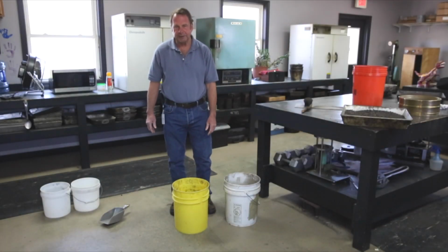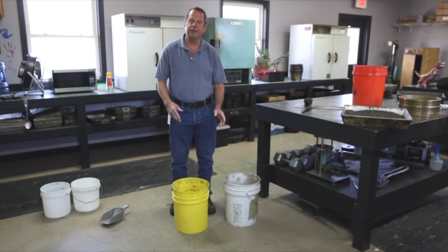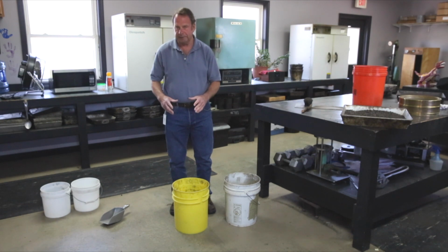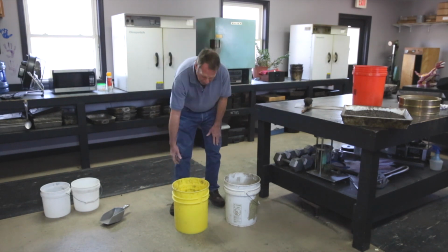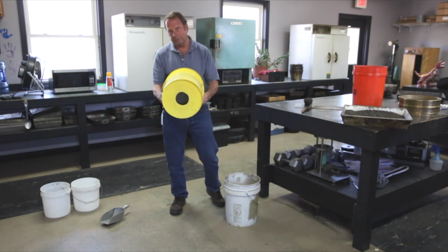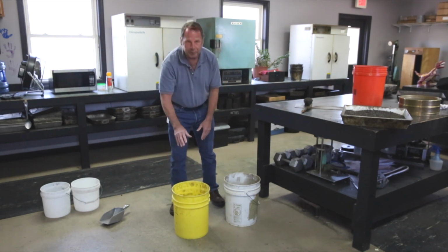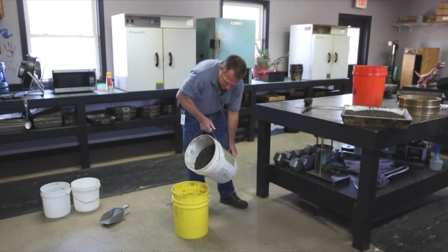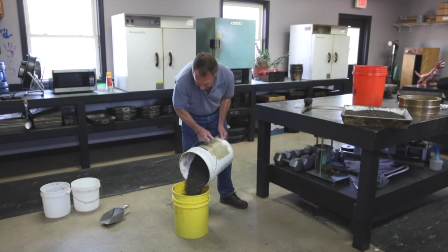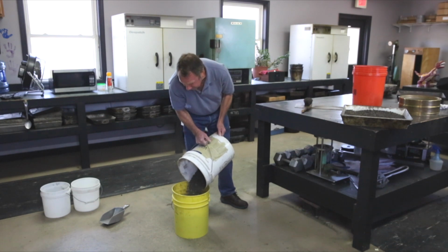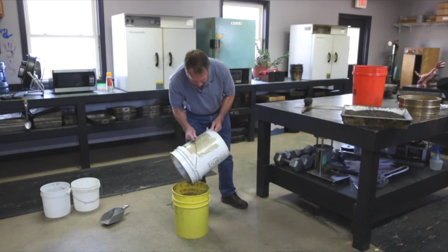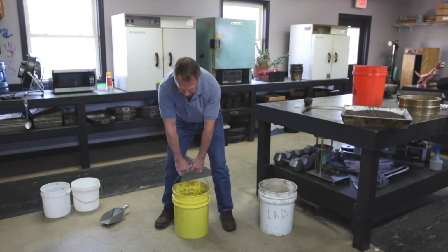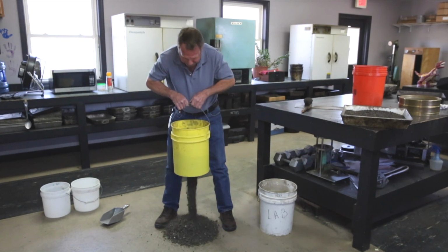We're going to do a demonstration on segregation with RAP out of a stockpile that you're going to put in your plant and show that the gradation and the binder content can vary depending on the way you work the stockpile. What I've got here is a 5-gallon bucket with a hole cut in the bottom of it. This is what I'm going to build my stockpile with. And then here we've got a 5-gallon bucket of RAP that's been processed. Okay, so it's gone through the process, and now it's going into the stockpile.